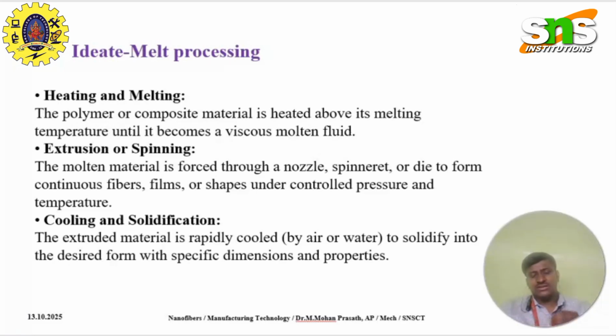First, we will discuss melt processing in detail. Melt processing is one of the techniques used for the production of nanofibers. The steps involved in melt processing are heating and melting. The polymer material is heated above its melting temperature until it becomes viscous.